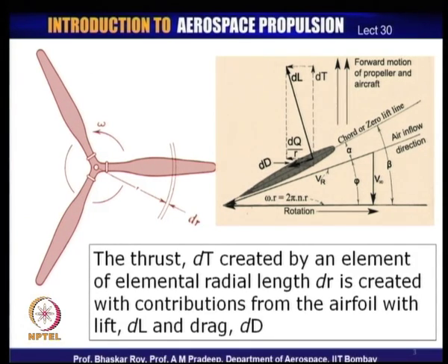So, as a result of which you get a thrust now born out of the lift component of the propeller. Of course, here you would get a very small negative thrust in the actual direction. So, the net thrust would be composed out of positive contribution from the lift and a small negative contribution from the drag. On the other hand, if you take perpendicular to the thrust in the peripheral direction, the two components of the lift and drag are actually additive, and they together create a force.